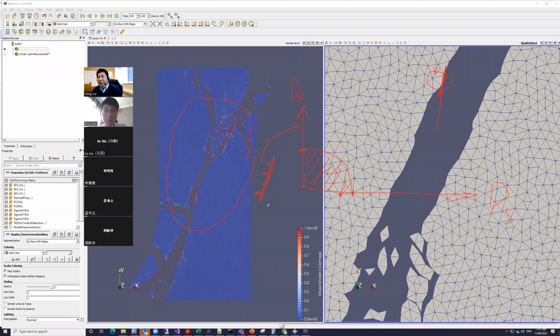Similarly, for shear failure, all four integration points need to fail in shear. Since pure tension and pure shear are difficult to occur, we can instead define tension failure as when even one of the integration points fails in tension.